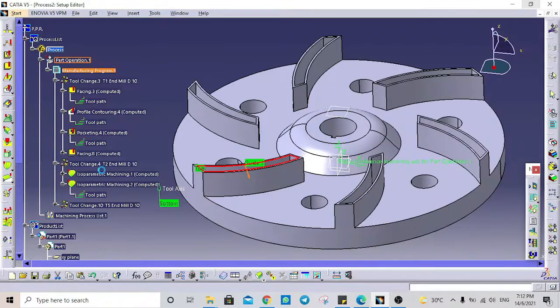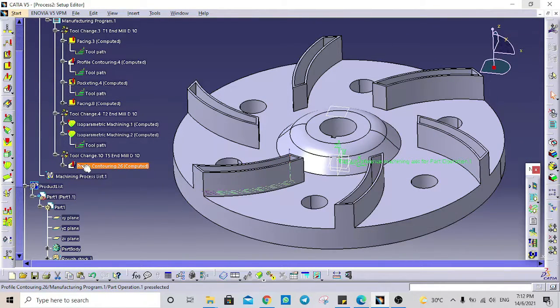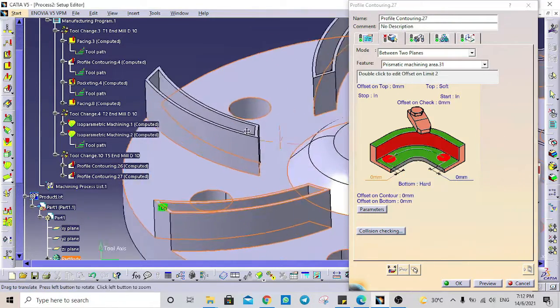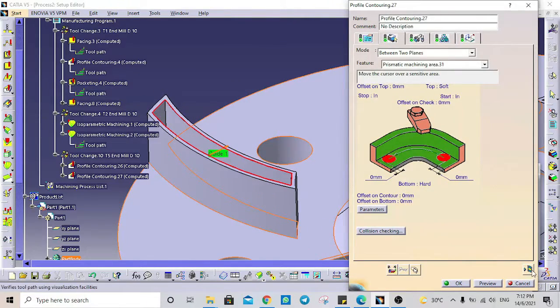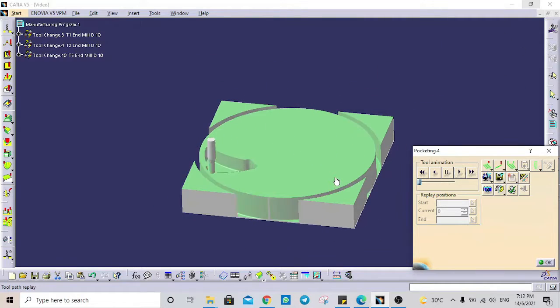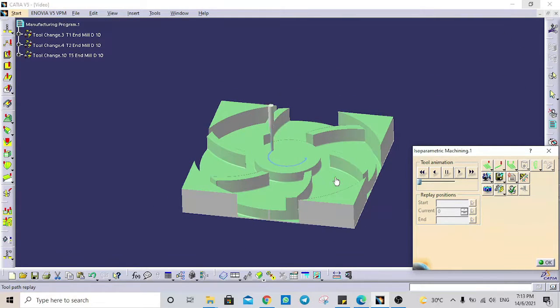Next is for second blade shell by using the profile process. Select the plane for the second shell process. And by using the same parameter of tool and cutting method, run the simulation for second shell process.